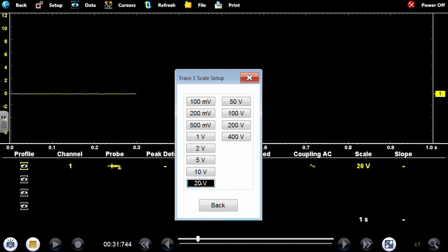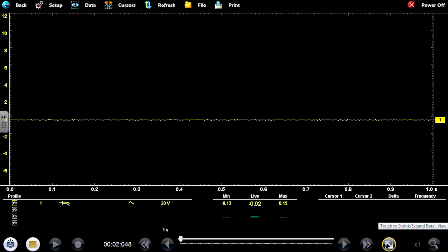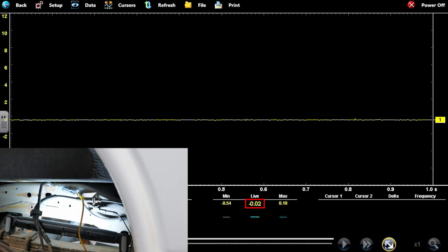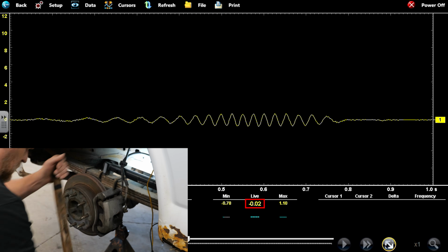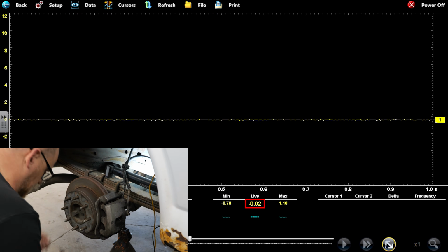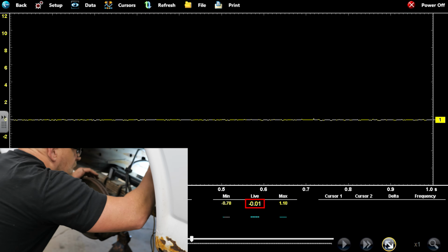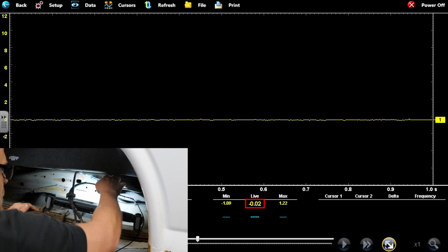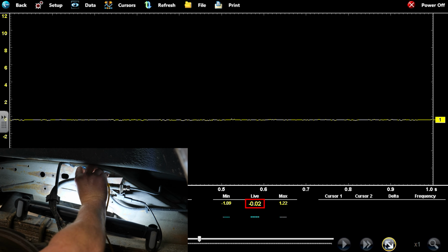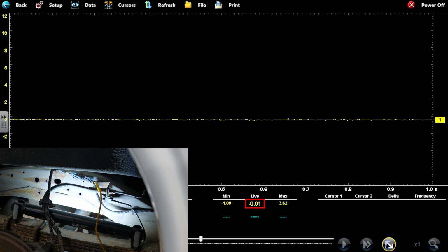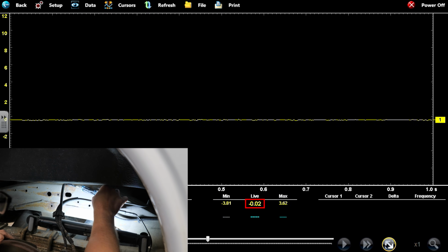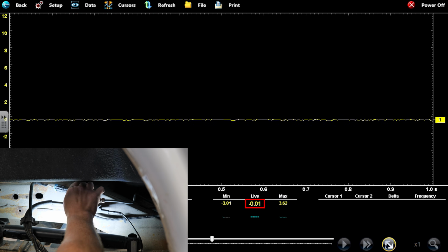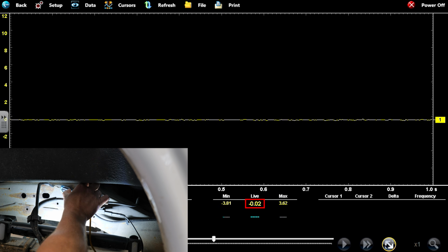This 0.76 of a volt is going to be 5 volts if I unplug it. So let me change that to 20 and let's get that signal back. Where did it go? I was showing 0.76. What happened to that? That's now showing 0, but I'm gonna unplug it real quick. Should go to 5. It just flagged a fault. You hear it. It stayed at 0. Going back to the top wire. 0 volts there, unplugging it.